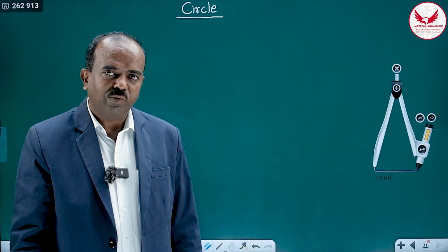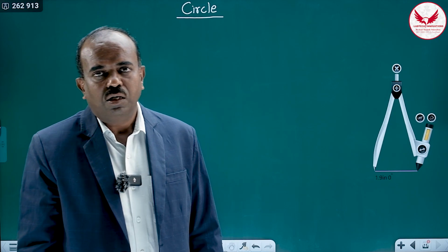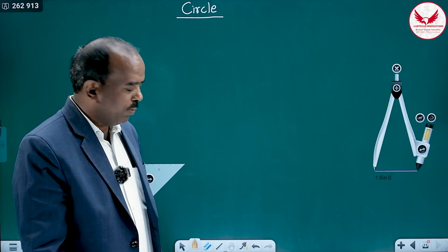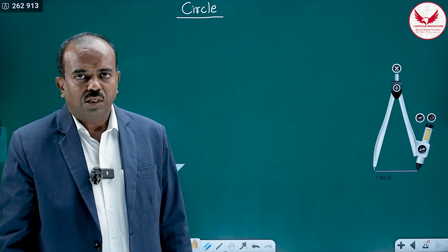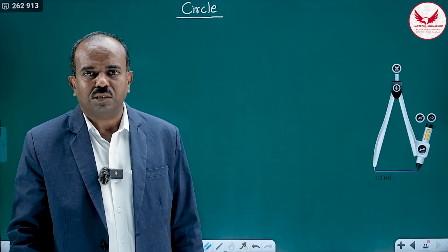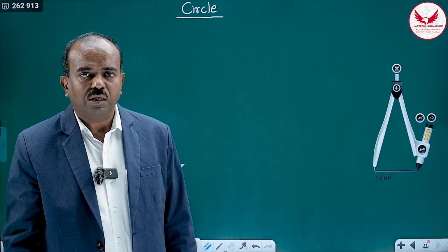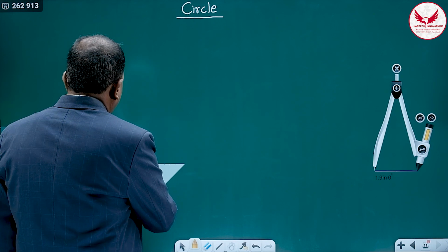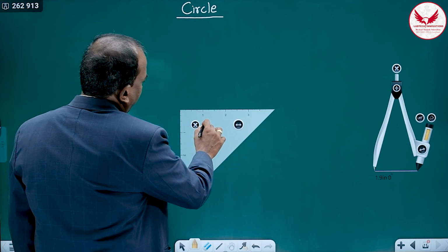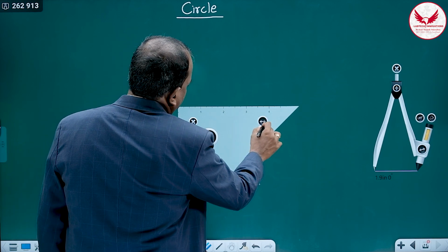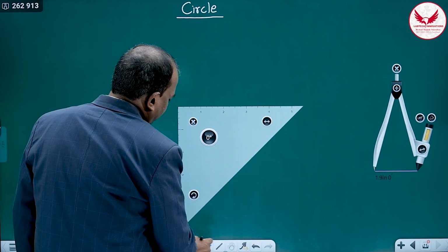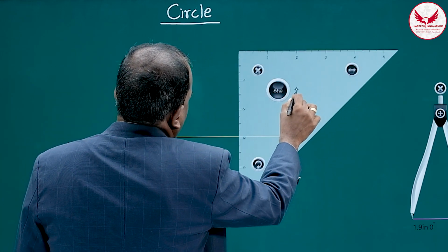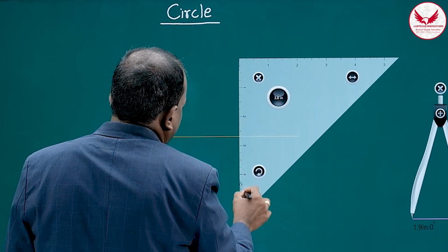Drawing a circle is very simple. With the help of the compass we can easily draw it, but the way in which we draw it is very important. So I'll suggest the proper way of drawing the circle. Never draw the circle directly by keeping the compass at some point. Instead, mark its center properly. The proper way of drawing the circle in graphics is something like this. In the beginning, draw a horizontal light line, then draw its vertical intersecting line.